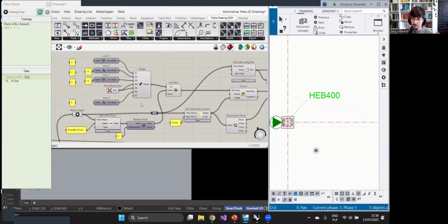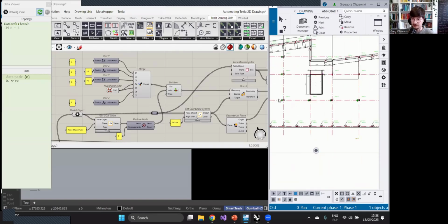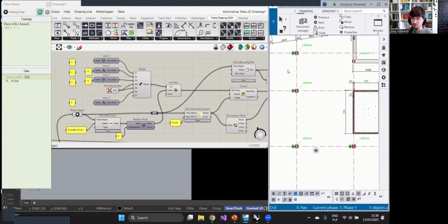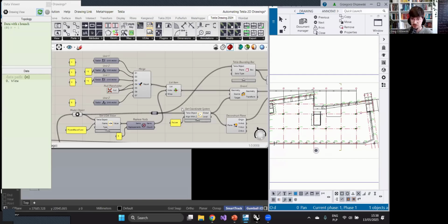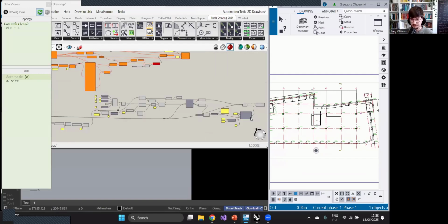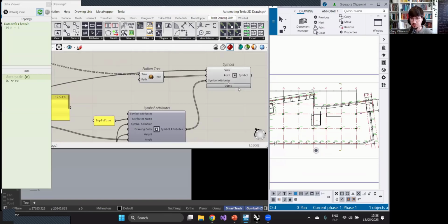And when you mix the powers of the live link and the drawing link, you will be able to place those symbols like now. So every column now would get it done. Of course, in that sample model, they are all oriented in the same way, but you can guess that in the real world, some industrial building, it could be done differently, and you will deal with hundreds of columns, maybe, yeah, dozens. So this is something that you can also do with the drawing link.